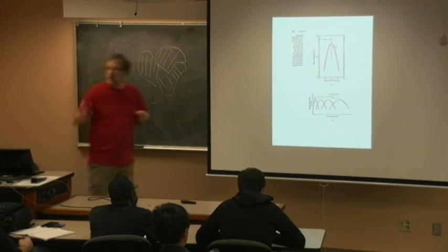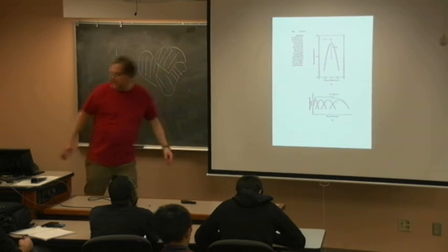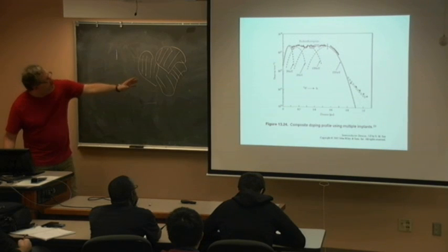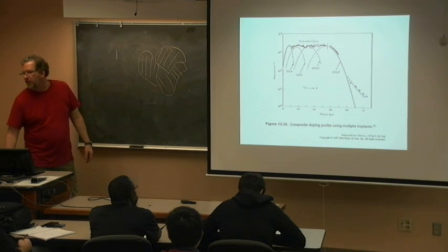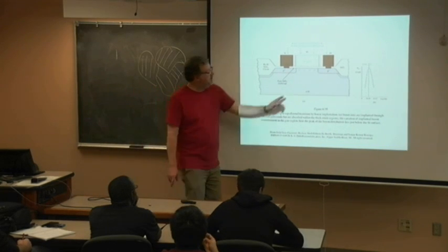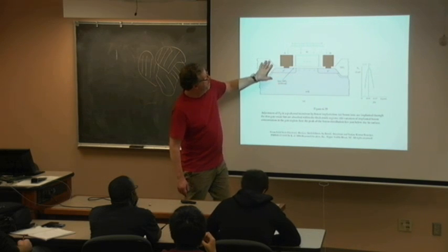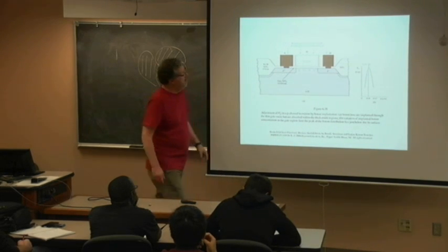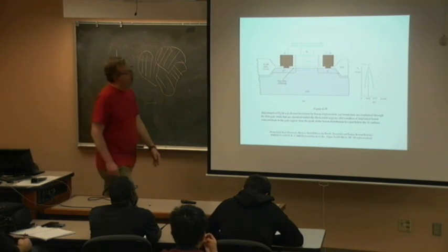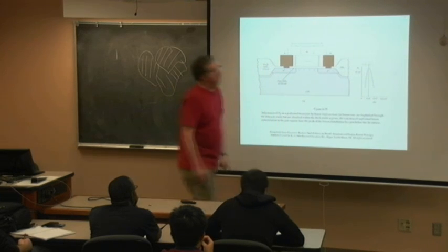But we can do the modifying of the doping, right? This is one way. It's kind of a crude way. There we did 4 different implantations, creating 4 different doping profiles. Now we are going to get back to this. This is a slide foreshadowing the transistor, where we will do ion implantation and finish up our planar transistor. That was a real workhorse in the transistor technology. So we could put that implantation precisely at the SiO2 silicon interface.